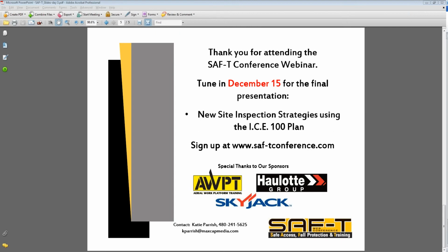If you're doing work in downtown Boston or something, and you're not sure about what's under the sidewalk, you may have to contact the city or an engineer with the municipality wherever you are to determine whether or not there is a sewer main underneath you or whatever type of service that may be there.